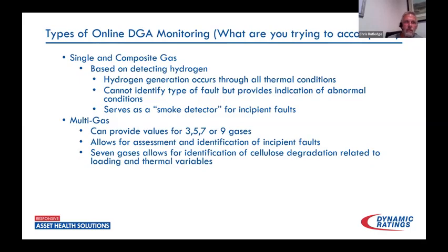And one of the main issues I take with this is there are so many other major failure modes of transformers that are being ignored. So, I mean, you have internal tank failures, but also bushings. What kind of shape are those in? So obviously power factor, tan delta, and capacitance of those would be something we'd have to consider. LTCs are another thing that we would want to monitor. Through faults are a huge thing, as I feel that through faults are one of those things that really don't even get looked at in concerns to transformer health.